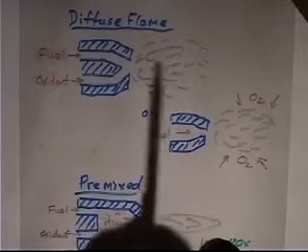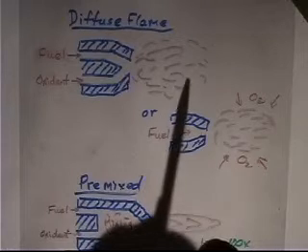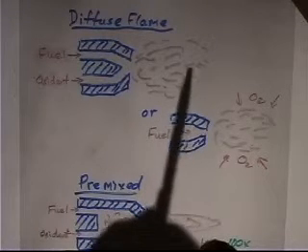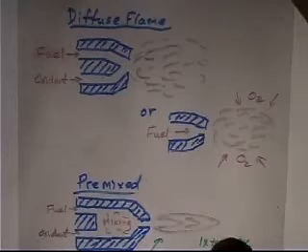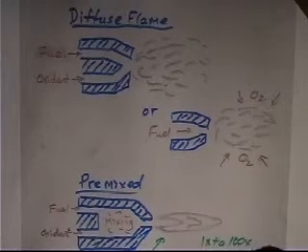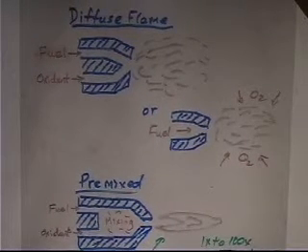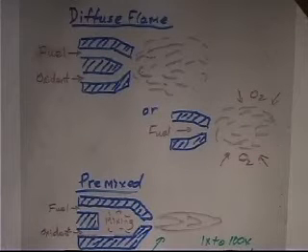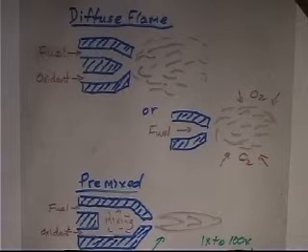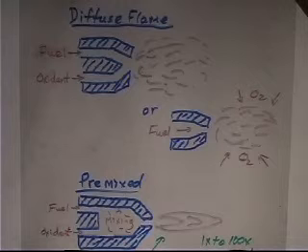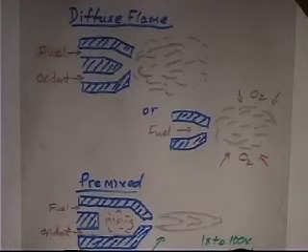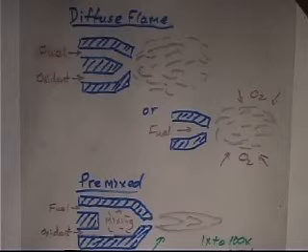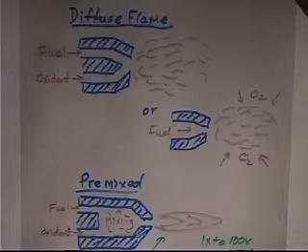And the temperature of a diffuse flame is going to be lower than the maximum temperature because you're not burning at the stoichiometric ratio. You're burning at the lowest ratio of oxygen to fuel that will support combustion, and that's not going to be the stoichiometric ratio in general. For example, if you look at flammability limits on different materials, acetylene has a flammability rating from like 3% acetylene in air to 80% acetylene in air. So that's why acetylene is sort of a dangerous gas. In almost all combinations with air, you can get a flammable mixture that's going to burn.